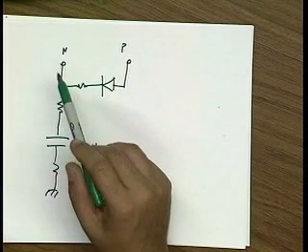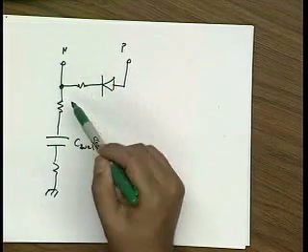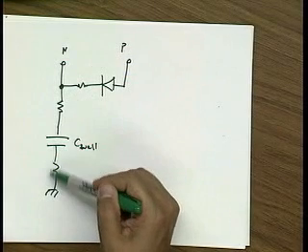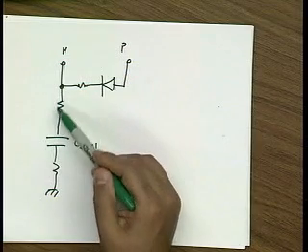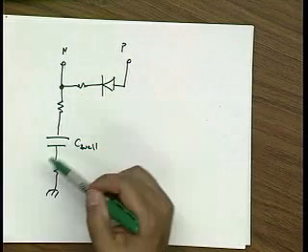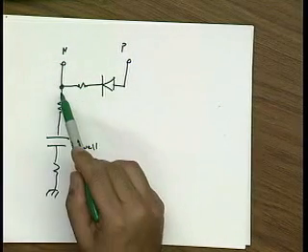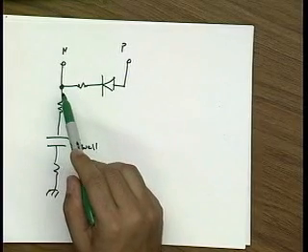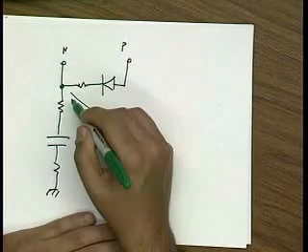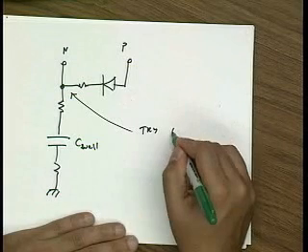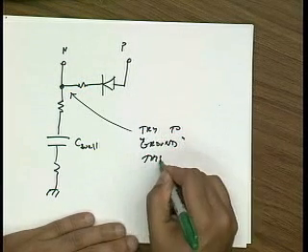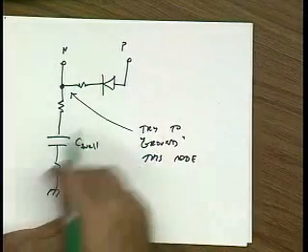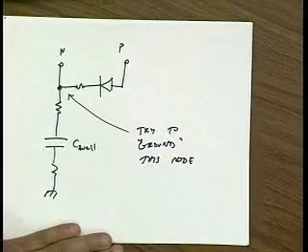Because if a voltage swings on this node, then current will go into this branch here, and basically you'll get loss through this resistor and this resistor, and so that will de-Q the tank. So really I would like to ground this node. In other words, I'd like to choose an oscillator topology where this node doesn't move.